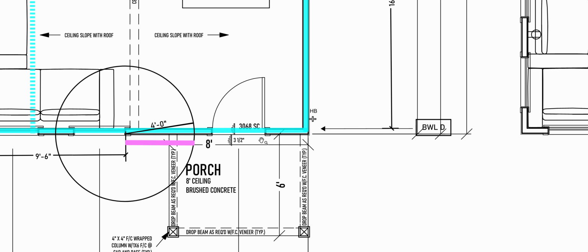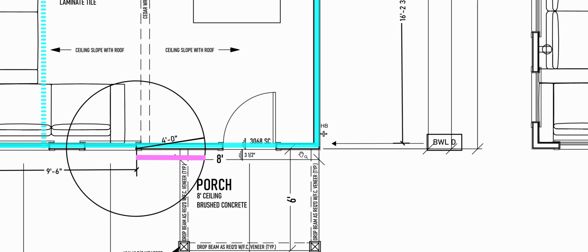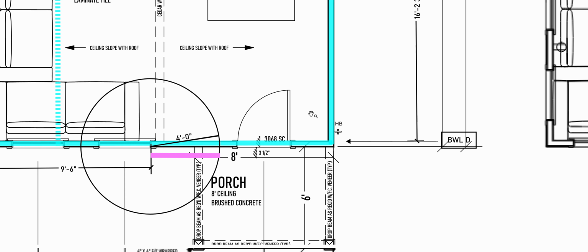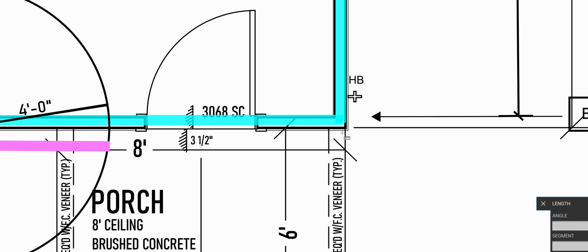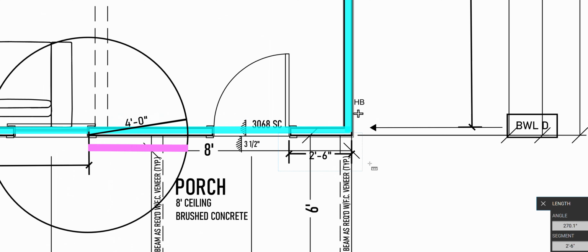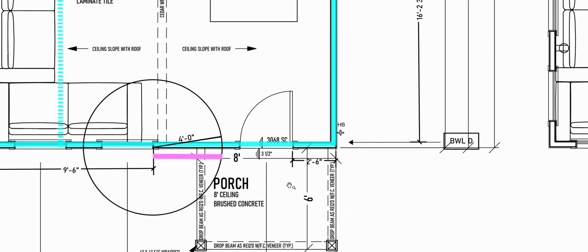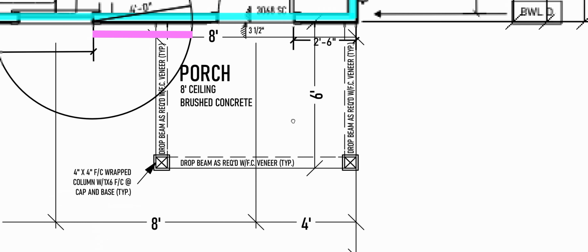Well, I have to know the opening height of the door is a 3068, so that's 80 inches. So I'm going to go check the requirement and see what size panel I can fit here with an 8-foot ceiling. Well, it's technically taller than an 8-foot ceiling, so I'm probably going to go up to 9 foot for this little portion here because it's getting taller as we go up. Okay, so I can do a 30-inch, which is 2.5 feet. Oh man, that's tight. It's a 3068 door, 4 feet from the end.